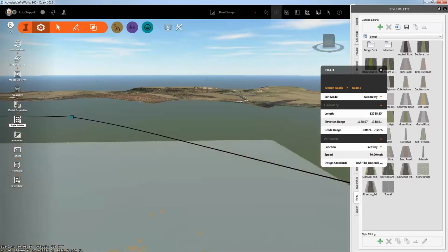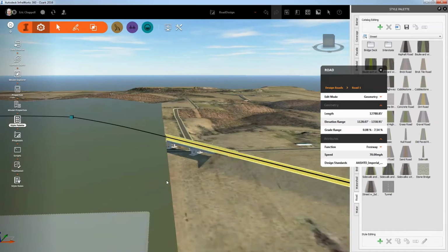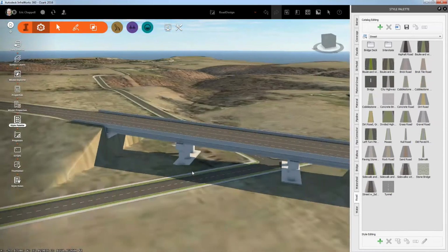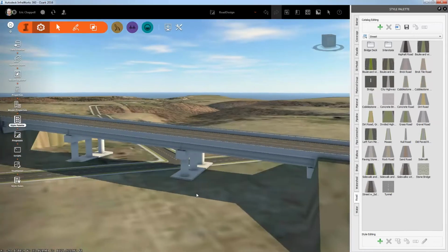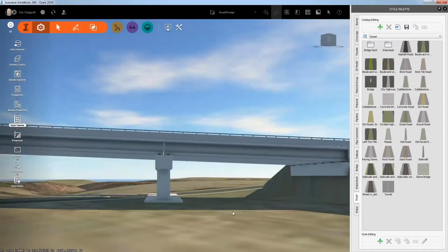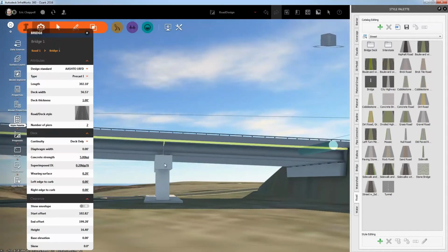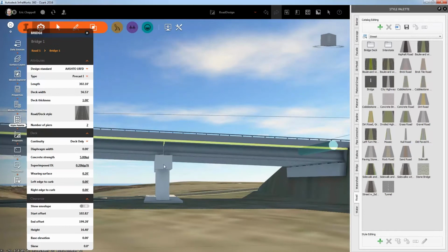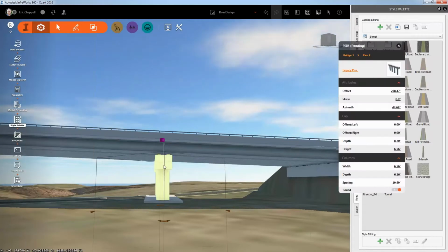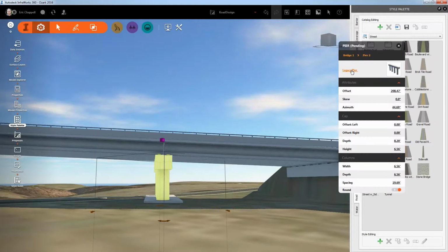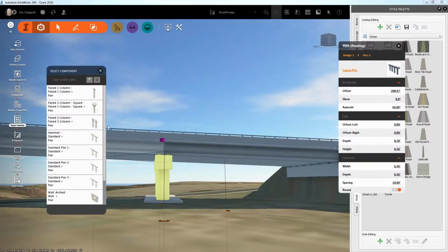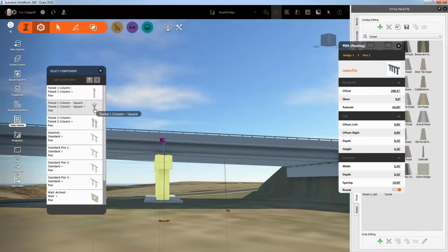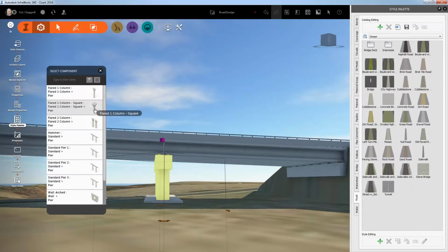But what I want to show you is the new ability to assign textures to these components. So here's some bridge piers under here. Need to do a little work with their placement and rotation. But you'll notice when I click on the bridge, that selects the bridge, and then I'll click on this individual pier component. It's a legacy pier right now, so I'm going to switch that to one of these other new pier styles that became available in the previous release, or maybe one before that. So we've got lots of cool pier styles now.